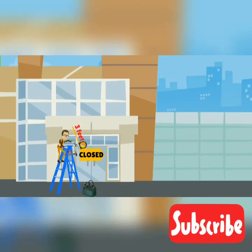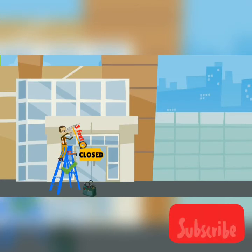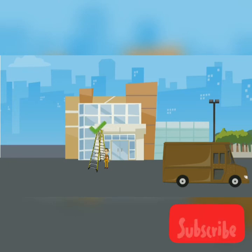Use a stepladder that is about 1 meter or 3 feet shorter than the highest point you have to reach. This gives you a wider, more stable base and places the shelf at a convenient working height. Place a stepladder at right angles to the work, with either the front or back of the steps facing the work.